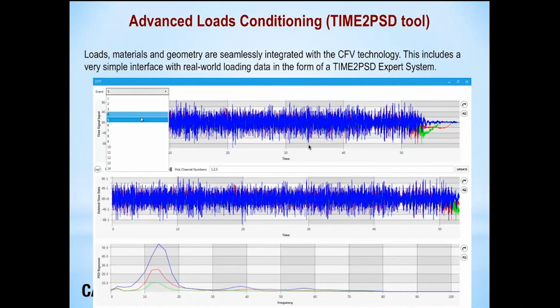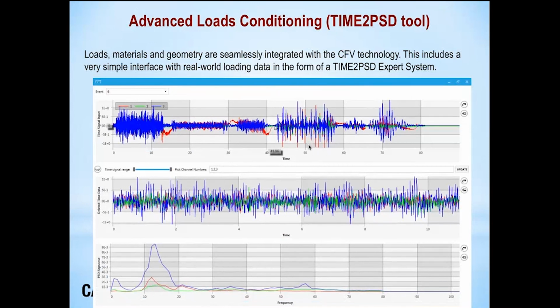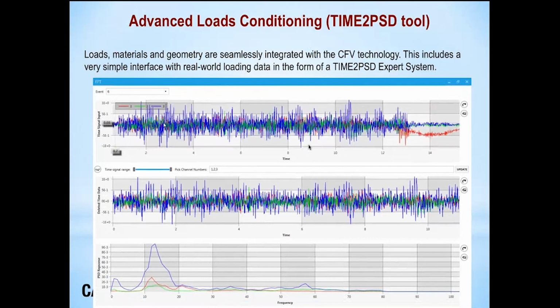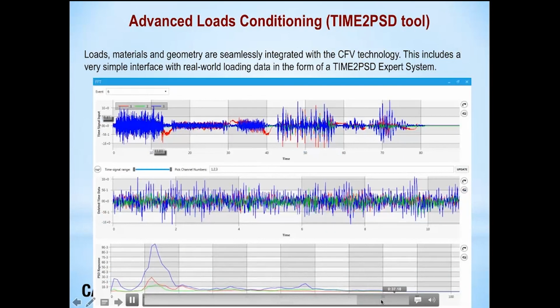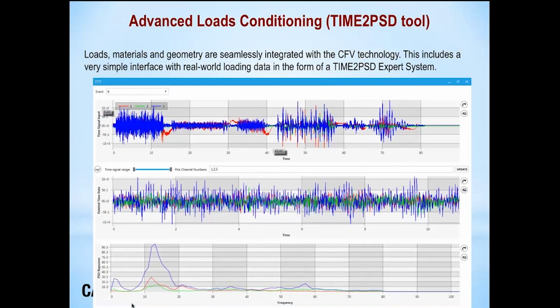Now, the key thing here is the conditioning involves several things. One is we have to make sure that the non-stationarity of the data in terms of its frequency content is taken care of, as well as the non-stationarity in terms of its intensity. So there are 2 parts to that. First of all, we have to apply what we call deletes to make the non-stationary frequency content stationary. So we split the data up into smaller events. And then we further process that to remove parts which don't belong because they don't have sufficient intensity. We've also implemented an automation which calculates the window length automatically. That's the Fourier transform window length that is such a hard thing for a user to calculate. So we've already got what we call semi-automated conditioning, and we're working hard to fully automate this, and we're confident over the next few weeks and months that we'll have that full automation in place. We think this is a really big step forward in the overall field.